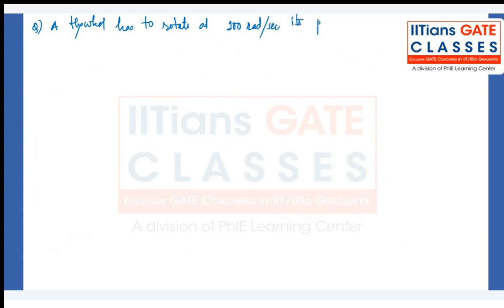Its permissible hoop stress is 320 megapascal, and its density is 8,000 kg per meter cube. Okay, 8,000 kg per meter cube.